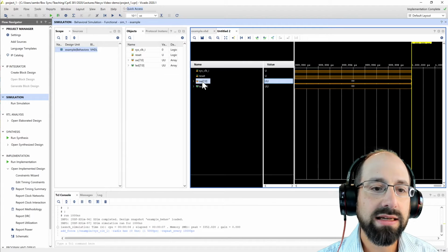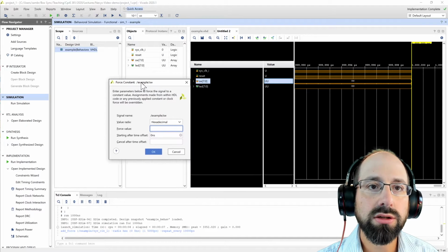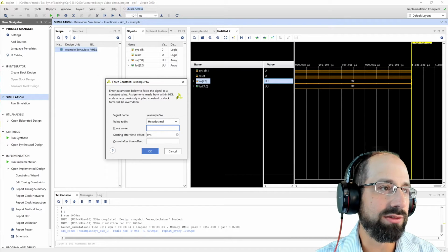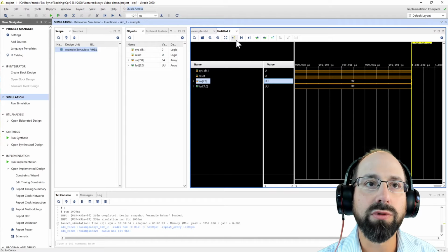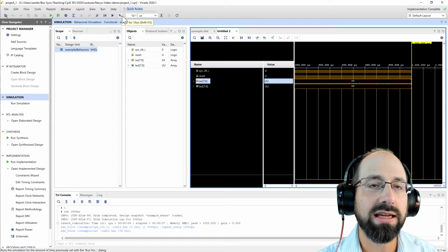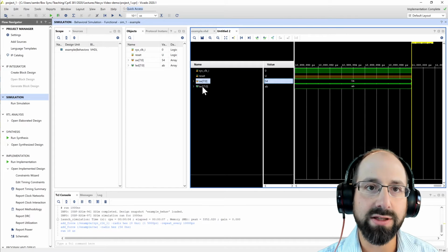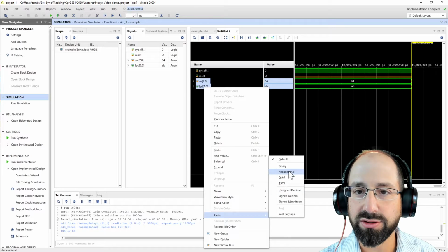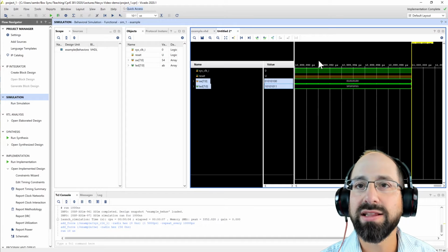Let's also set our switch, our input value here, to a hexadecimal value. What would be an interesting value? I don't know, 54 hex. And then we should be able to run it for a short period of time, which again is kind of hidden. There's a million little tiny options, just like ModelSim would have. We run it for a short period of time, and then if we wanted to convince ourselves that this was actually correct, it does look correct, but maybe mapping it to binary would make it more obvious that it's doing the inverting, and it's doing it at the rising edge of the clock.